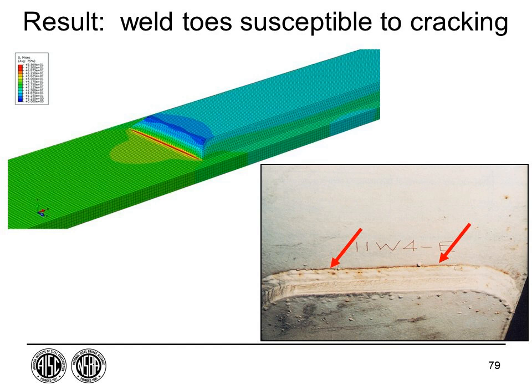technically you could. You'd have to use fracture mechanics to begin to try to infer what that was. So if it had a defect in it, say you knew it had a 1/8 inch crack, you could keep your stress ranges below what's called the material, I can't think of the term what it is now, but it's a material property of when the crack would be expected to grow.